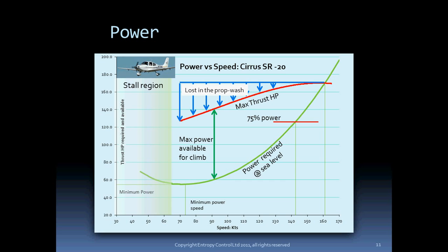But in fact, the curves are roughly parallel in that region, so the climb rate does not decrease much if the speed is increased a bit. Increased speed gives you better engine cooling and in fact better prop efficiency, both positive effects. So generally, where possible, you'll use the cruise climb speed rather than the maximum climb speed. Throttling back at 75% power, the thrust horsepower is about 124 horsepower, yielding a cruising speed of around 142 knots.